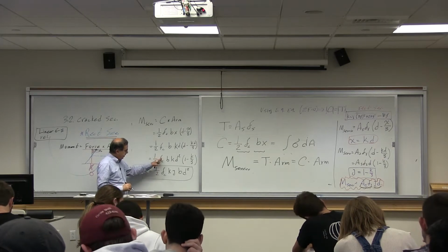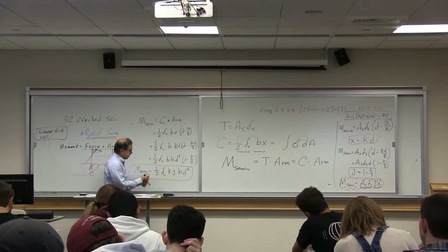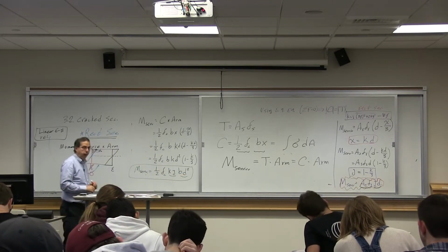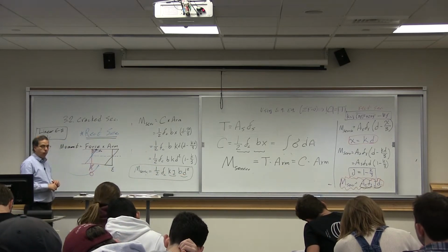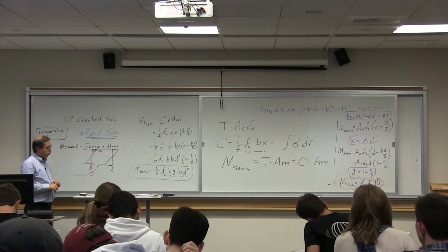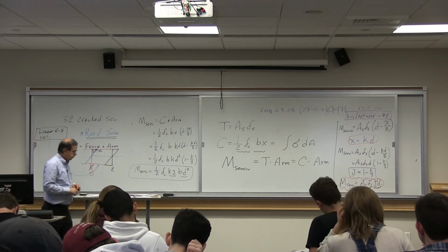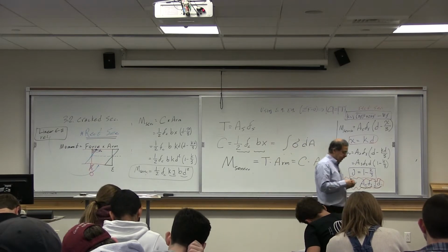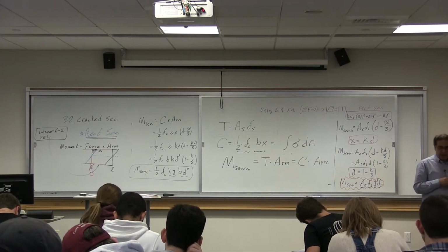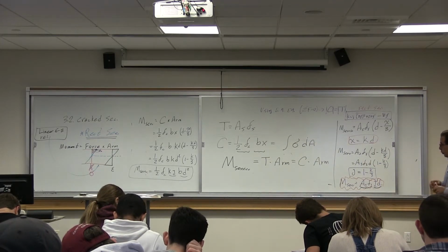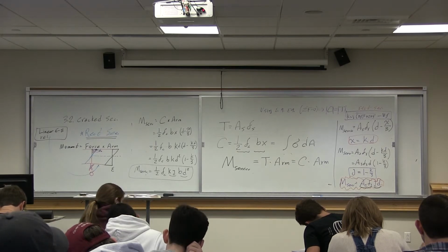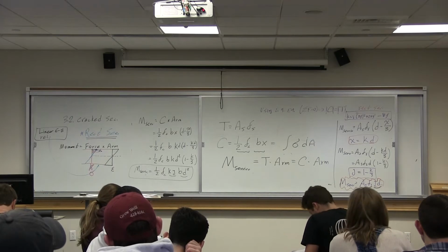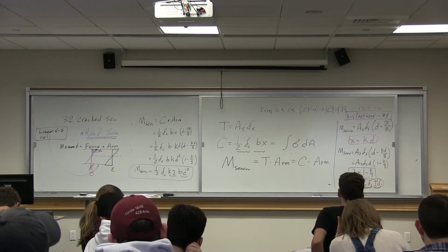I just rearranged these terms, put kj first, then b d squared. So this is how we relate the stress in concrete to the service moment: 1/2 of fc kj b d squared.